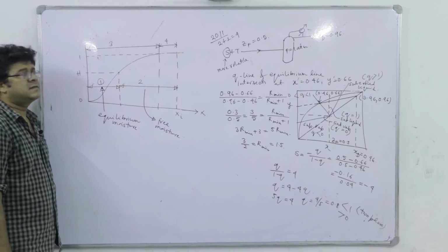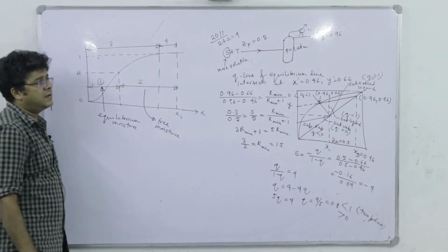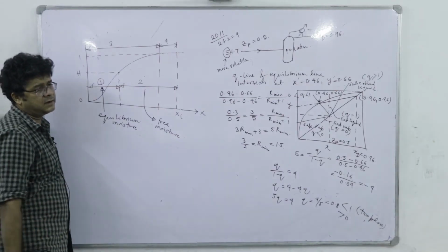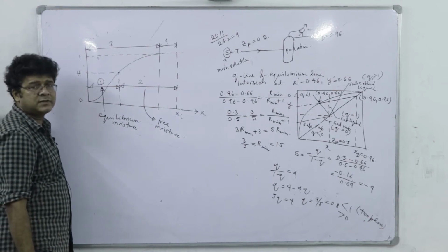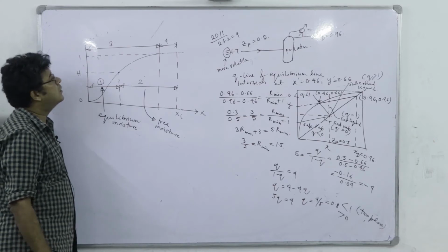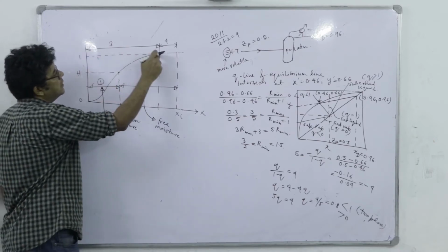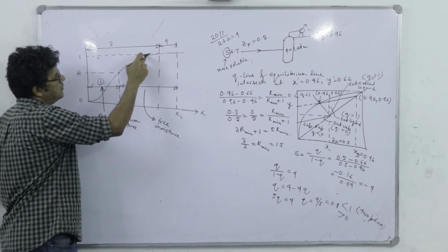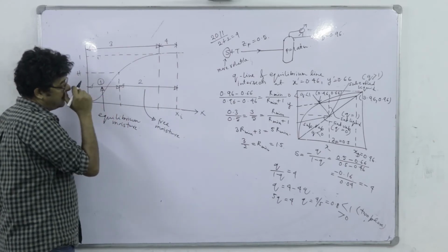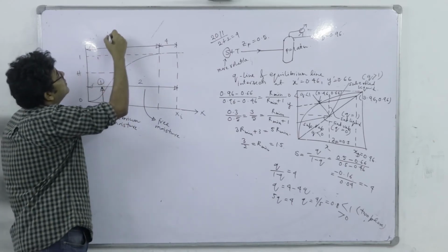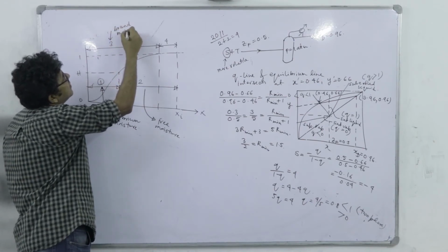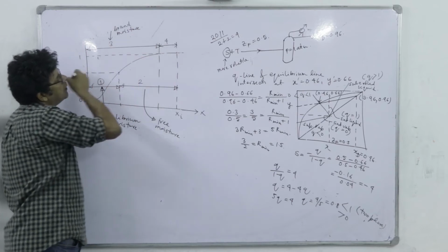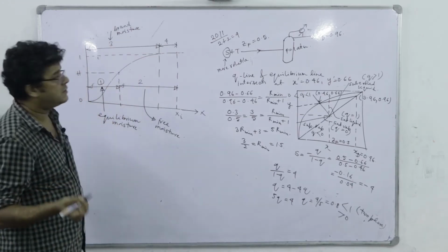Now when the exerted vapor pressure of the water vapor by the solid is less than the pure water's vapor pressure, then we call it bound moisture. So here, up to this, the exerted vapor pressure is less than that of Psat. So 3 is the bound moisture, and whatever is above bound moisture is the unbound moisture.